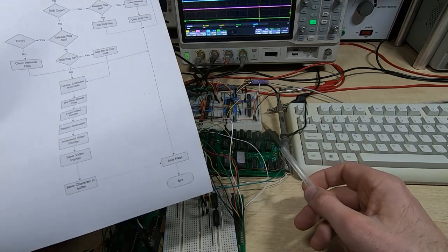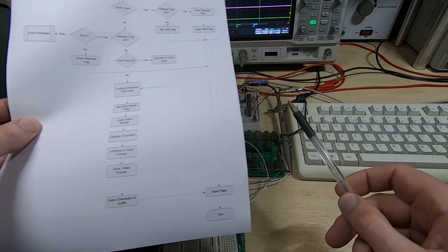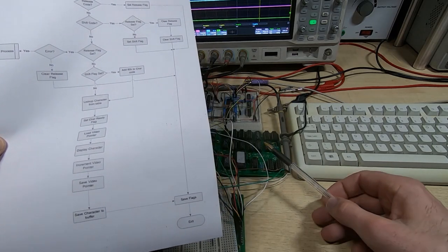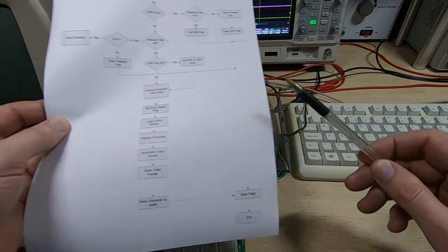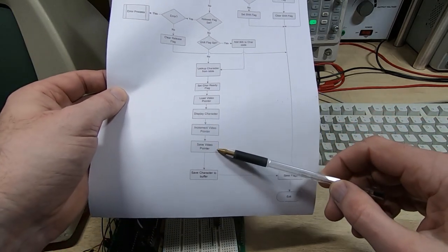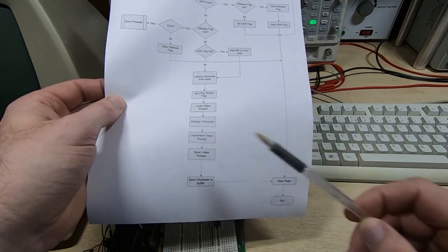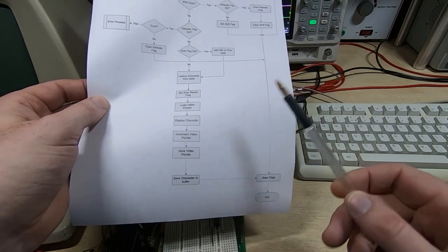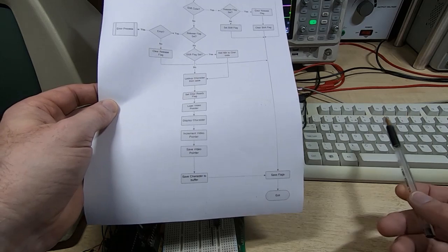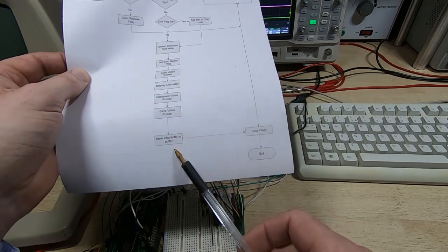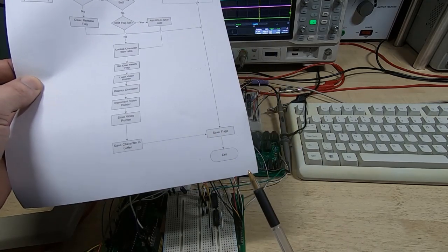When we come to writing the full handler for the Z80, the boot ROM, we'll deal with what happens to the character that's been pressed in the main part of the program. But for now, I'm just using a very small loop within the interrupt handler to send that to the screen. As I say, later on we'll have a circular buffer that stores the characters being sent from the keyboard. In this case it also saves the character to a buffer, exits, and that's it.